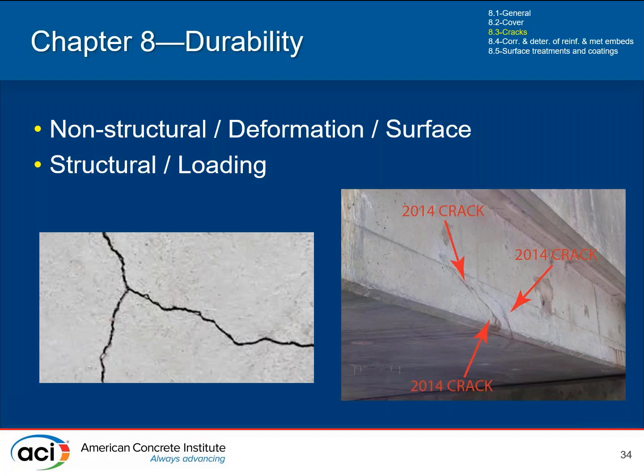If it's really a narrow crack, a thin crack, maybe you don't need to do anything. It's not really letting in much water and it's not having an impact. But if it is letting in water, maybe we do need to inject it, or maybe we do need to provide a coating to keep everything out. If we just have one crack, maybe that's a good candidate for injection, whereas if you have 1,000 cracks, you need to consider whether it needs to be coated.